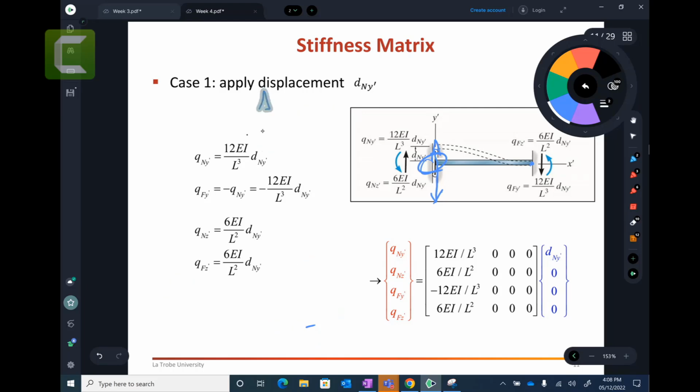What I have done is, you understand that this beam element has 4 possibilities. It can go up and down at the left side. It can go up and down from the right side. That is 1, 2. It can rotate, number 3. It can rotate, number 4. So there are a total of 4 different degrees of freedom. Out of 4, I remove 3. I fix them. I make them 0. I leave only 1 possibility. Yes, so far so good. In that story, you with me.